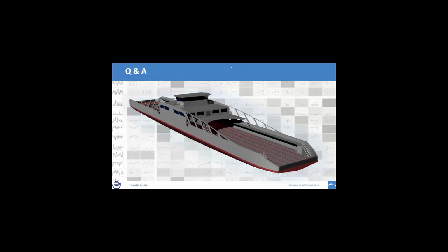I can do this when I create the definition for the parametric section. So I take into account the deadrise angle, for example, to stick with the model that I've shown, or the flare angle, and I feed that into my section definition. But the more difficult task sometimes is in the longitudinal direction, where it's mostly a question of keeping all the inputs to the curve engine continuous.